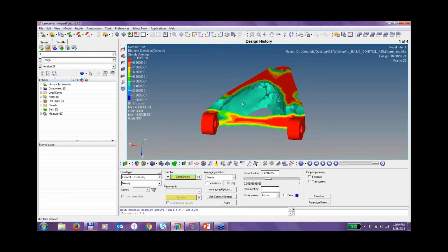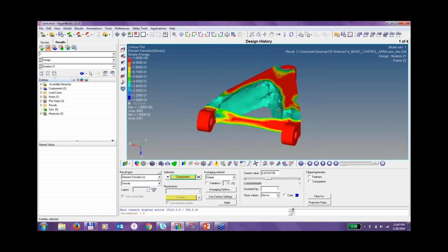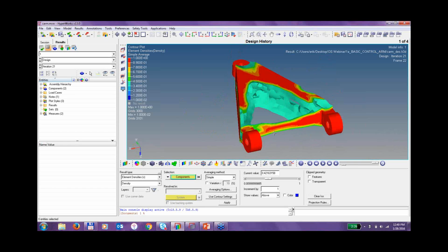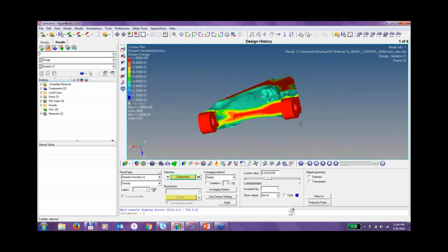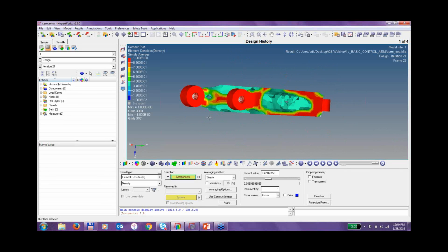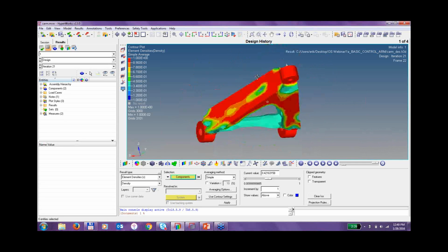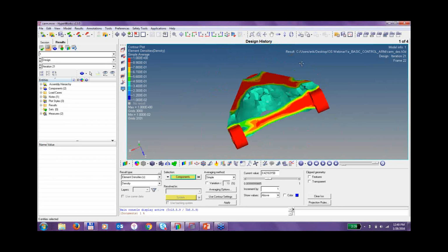It determines what elements are necessary, what elements aren't necessary. It carves away at the elements that we don't need. Think of it almost as a load path analysis. And you end up with a part design that you possibly would never be able to think of, because it's analytically determining which elements are necessary and which aren't. But of course, you look at this and you think, well, unless I'm using a 3D printer, this part can't be manufactured. It has cavities in it, and using no traditional manufacturing technique, stamping or casting, could this thing be made.